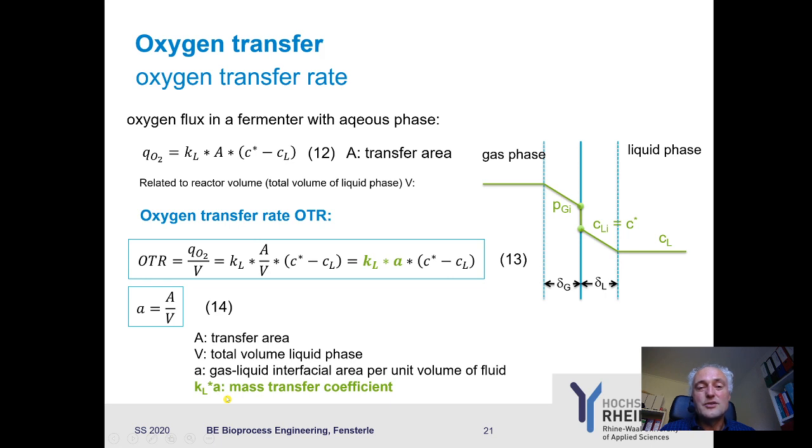If you talk about oxygen mass transfer in your culture, you determine the complete coefficient here, the KL together with A, and you don't care at the end what is what, but as you know it's surface and this constant, you of course know how to increase the transfer by increasing the complete term. So this is of course still important, that it's surface and this constant. However, as you cannot measure it, you treat it mathematically as one figure, because you can't measure each individual issue.